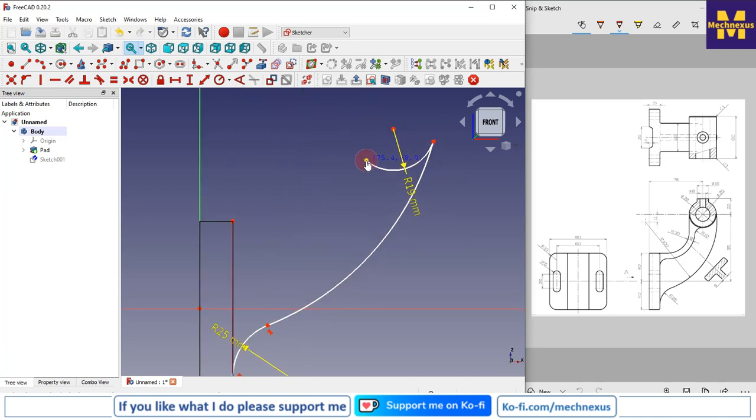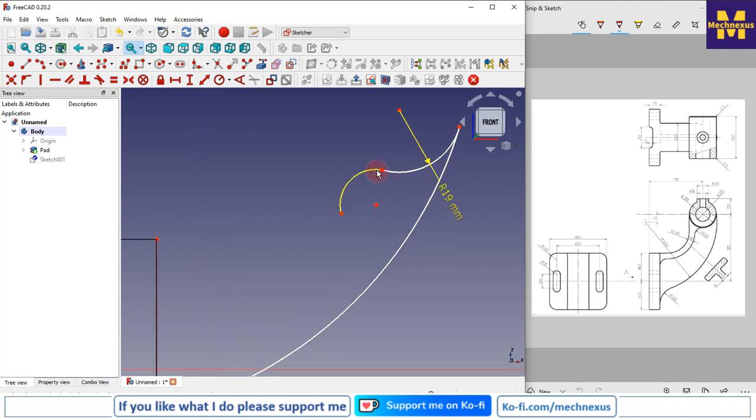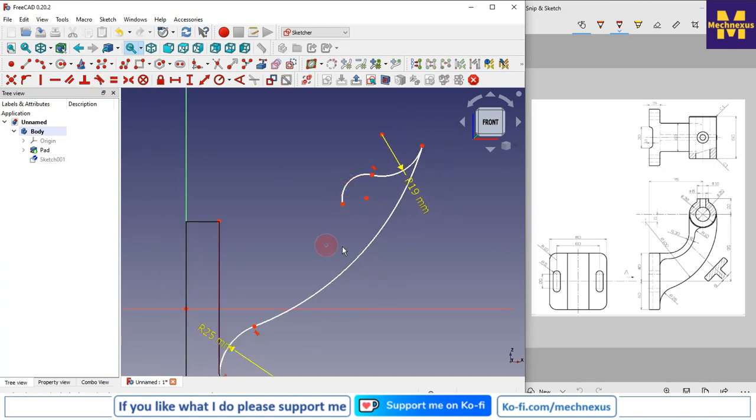I will make it something similar to this, and again I will draw a 3-point arc for this radius R10. I will make it tangent, and again a 3-point arc of R30.